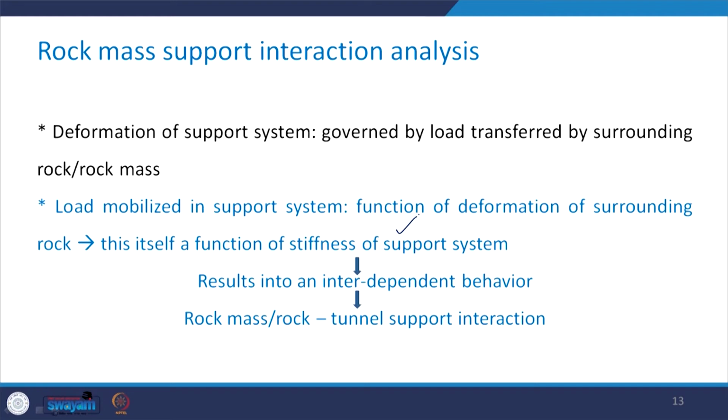This is a function of deformation of the surrounding rock, and this deformation of the surrounding rock itself is a function of the stiffness of the support system. So, you should be able to visualize that this whole phenomenon results in an interdependent behavior, and therefore this is called rock mass or rock tunnel support interaction.